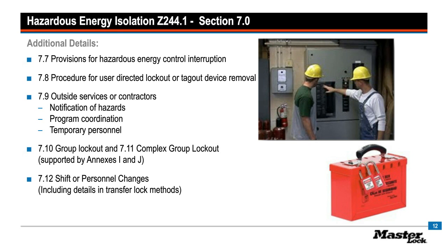We're trying to emphasize bringing down the practice of leaving locks behind on equipment that could later result in personal locks needing to be cut off in emergency removal type processes by addressing a transfer lock or maintenance lock type process that allows securement of machinery, not during personal exposure, which would require personal safety locks, but in transferring the ability to secure and remove securement from machinery over a period of time, allowing incoming workers to replace maintenance or transfer locks and replace them with their personal locks, then reestablish that the machinery is in zero energy condition before beginning their work.